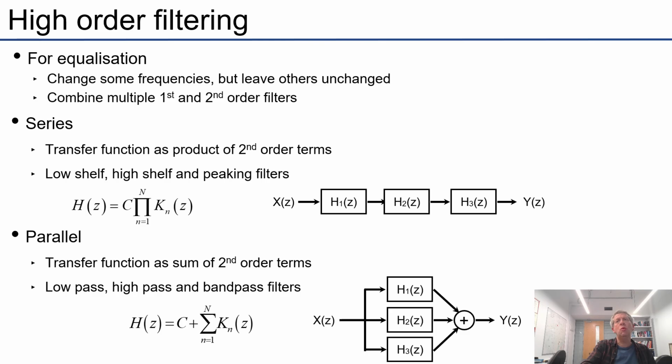Sometimes we do want high order filters, high order IIR filters. They can generally be made two ways. Well, they can be made many ways, but sometimes people have small lower order sections, like first and second order sections of the filter in series. So it goes through some low order frequency shaping, then mid range, then high range, and so on.